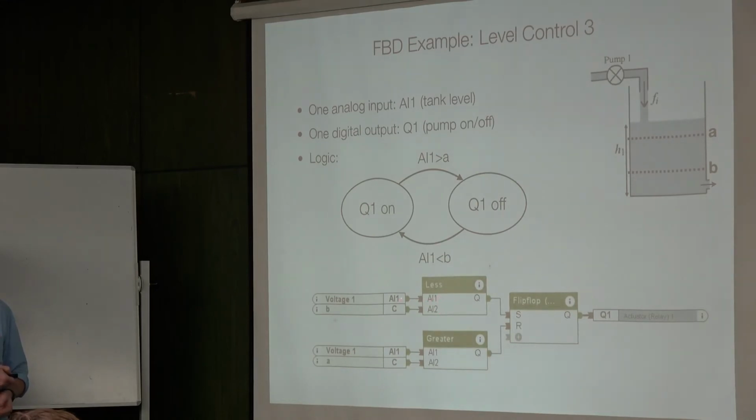Each block compares the first value to the second one and gives a truth answer. So here we have a 1, 0 output depending on whether this condition is satisfied. If it is, it will start the pump. And this condition is where the water level has increased above the upper threshold. It's the condition which switches off the pump.